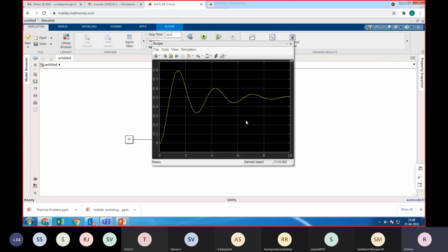So if it goes over a bump, depending upon the force, I've given the force applied as 10, so the bump should be a small force. For that, it takes 10 seconds. Similarly, you could simulate this damping system for different force conditions and see how these curves come. You could also bring in different spring constants. There are different types of springs. People who work on composite materials are nowadays working on even GFRP based springs. All those springs can be connected there and compared.